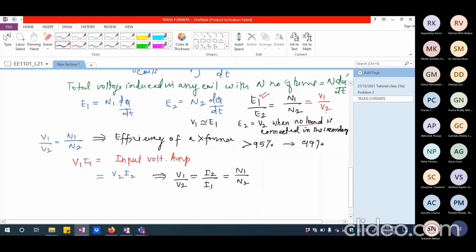So this is generally the voltage and current relationship in a transformer, which is excited by alternating current, and the secondary side is going to be connected to a reasonable load. What do we mean by reasonable load? If I say it is a 2.2 kVA transformer, I would be drawing a current that is close to 2.2 kVA, such that the output delivered is close to 2.2 kVA. So I'm neither talking about a completely open circuit condition nor almost short circuiting the secondary.